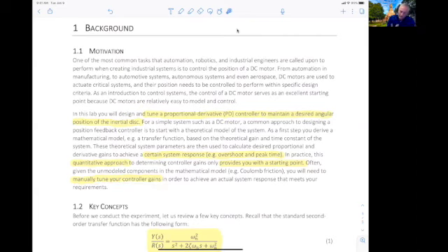A natural question would be, why can't I just start to tweak it from the beginning? And that's true. For this simple example, you could probably skip the modeling, hook this up in the right configuration, and have a reasonable chance of it working. That's because this is a pretty simple example, and the DC motor is fairly easy to model. But if the system gets more complicated, it becomes harder to just guess and check, so it's important to go through a systematic way.